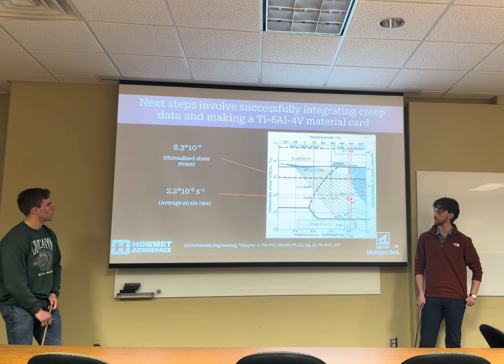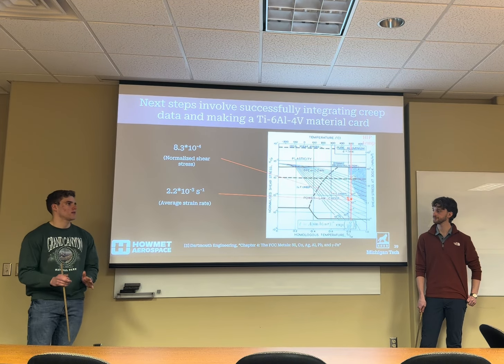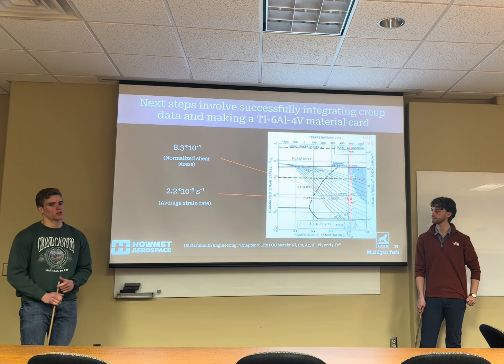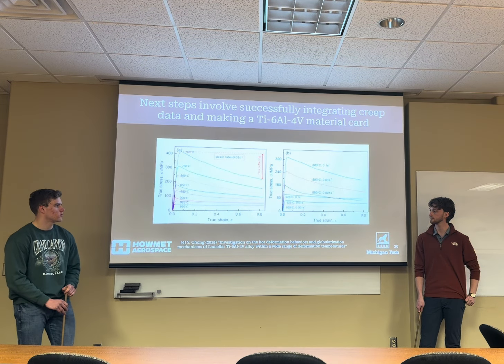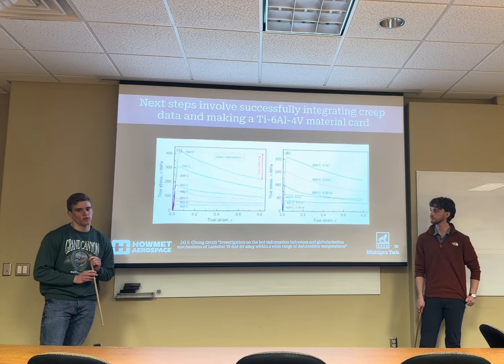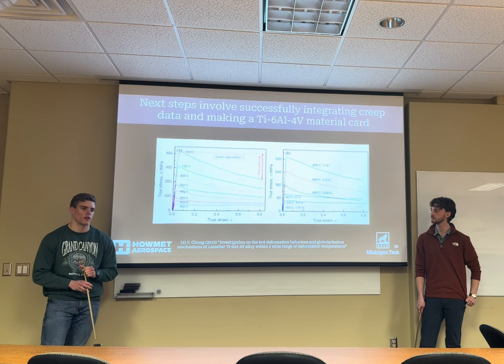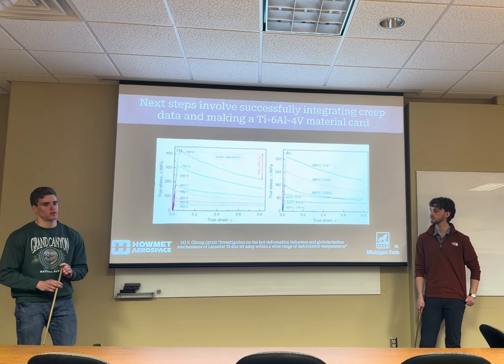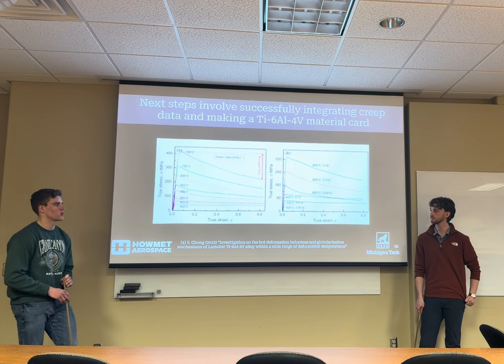So future steps are to integrate creep data into this model to help it make a better prediction for smaller pores. And we need to make a material card for titanium itself because we couldn't cast it here on campus, as it requires a vacuum induction melting system, which was currently under service when we started our project.